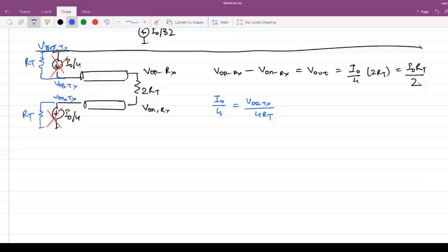Right? This is the simplest way I can get the same swing as what I was getting with the CML output driver. I can also have a termination on the transmitter side as I have drawn. I just put a 50 ohm resistance and a VDD-TX. Now you see that this output swing is dependent on the supply voltage, whatever VDD-TX I have used.